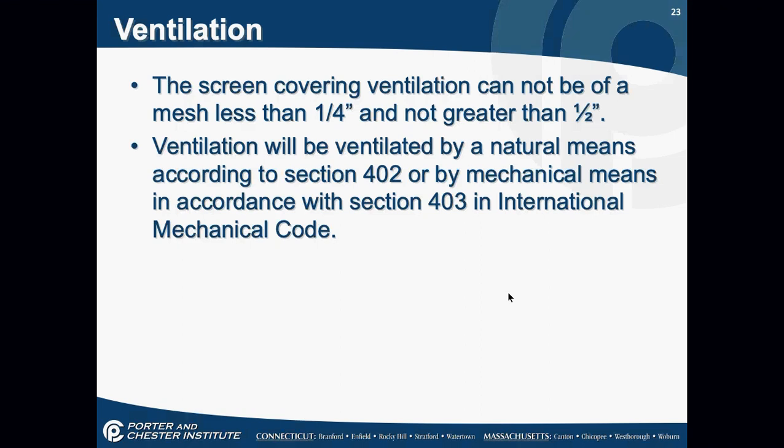The screen covering ventilation cannot be a mesh less than 1/4 inch and not greater than 1/2 inch. So the little holes in the mesh cannot be less than 1/4 inch and not greater than 1/2 inch. Why is that? Too big, and you can potentially get animals or debris inside, I guess. Yup. Exactly. Why too small? Why don't we want it too small? You still want the air to flow normally.